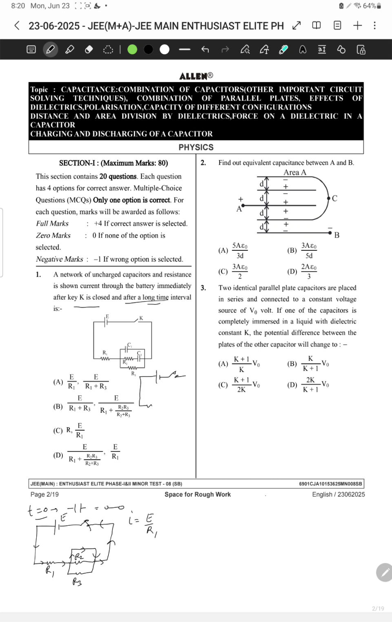I will draw the diagram again. There will be no current in this branch, no current in this C2. If there is no current in C2, there is no use of R2, so I simply remove it, because if no current passes through a resistor, there is no use of that resistor. So this kind of diagram we will see: R1, R3 and E. When the key is closed, the current will flow like this.